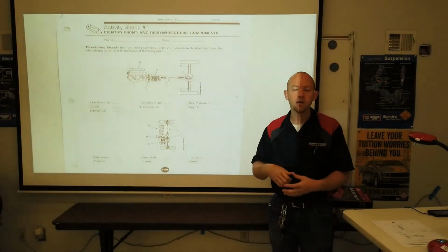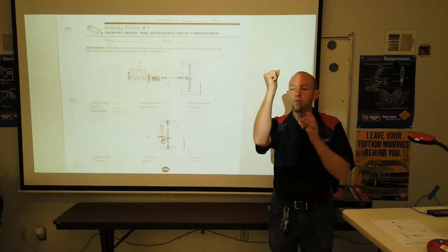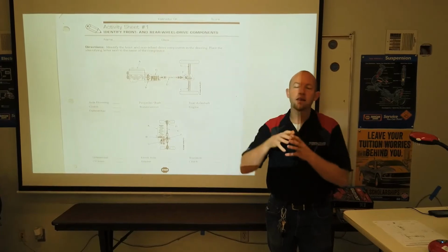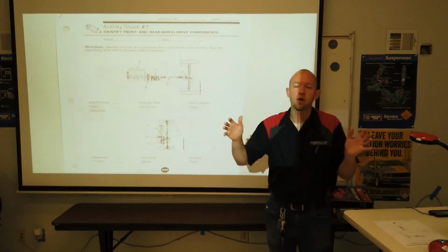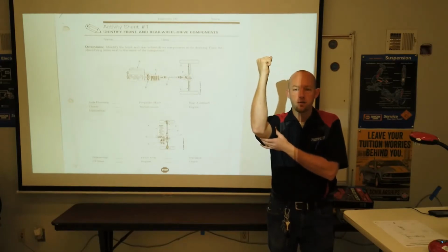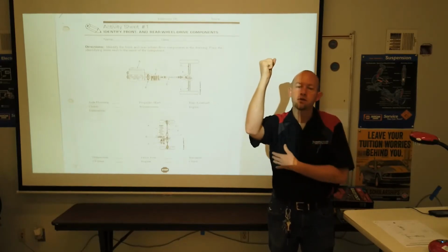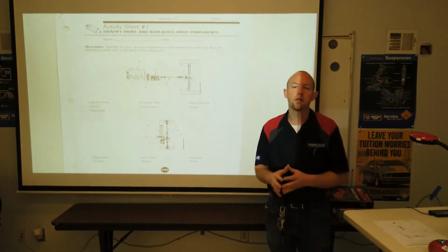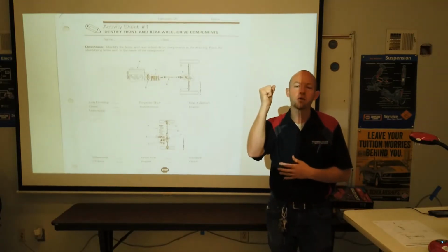Then right towards the end of the compression stroke, both valves are closed. We're going to have ignition take place, or spark, that's going to light that air-fuel mixture, and that air-fuel mixture is going to start to burn just after the piston peaks over top dead center onto the power stroke. Then we have maximum pressure on that piston, and we're pushing down and capturing all of that mechanical energy. Both valves closed on the power stroke.